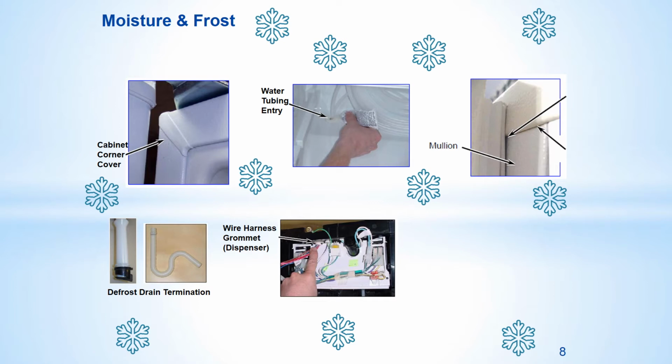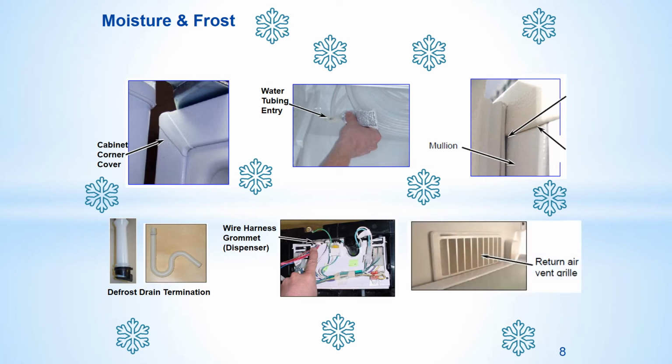Don't forget about the return air grill and duct, as ice or frost here will cause warmer than normal temperatures in that compartment. Be cautious when defrosting ducts, as even a steamer can saturate styrofoam or warp thin plastic. Removal of any frost accumulation is necessary, but that in itself may not resolve the root cause. The source of excessive moisture must be determined and corrected.